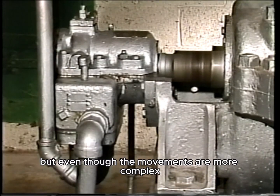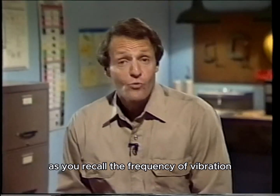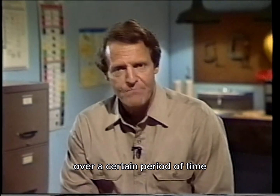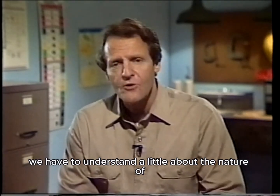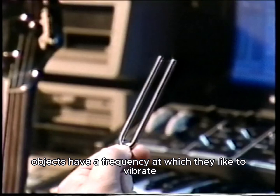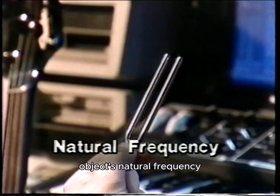But even though the movements are more complex, they can still be described by using the terms that we defined earlier. As you recall, the frequency of vibration is the number of cycles that occurs over a certain period of time. To understand how this relates to rotating equipment, we have to understand a little about the nature of the components themselves. For example, all objects have a frequency at which they like to vibrate. This specific frequency is called the object's natural frequency.